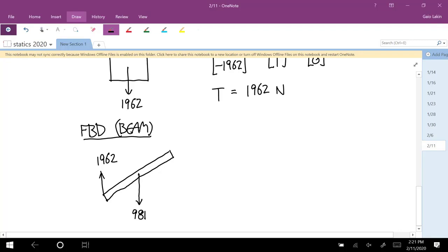And now this is the first time in one of these problems that we're using what we know about two-dimensional joints. So with that fixed joint at the right end, is there any axis where this can translate? No, so the x and y components both have forces applied, okay? There's no axis where it can translate.